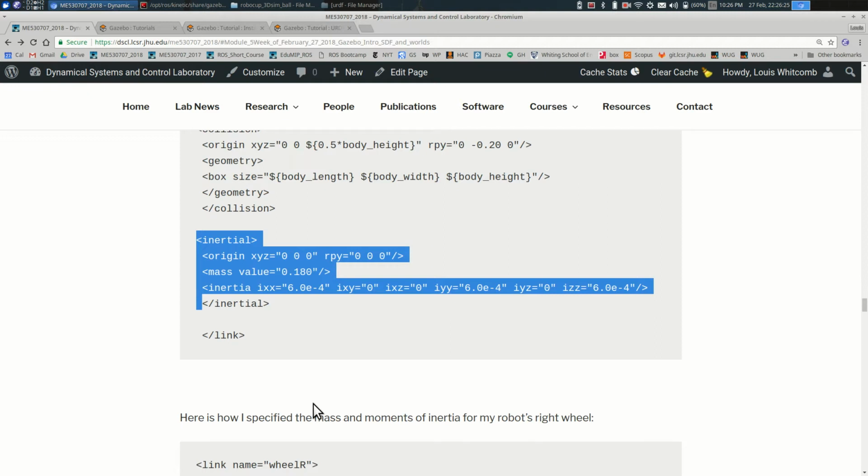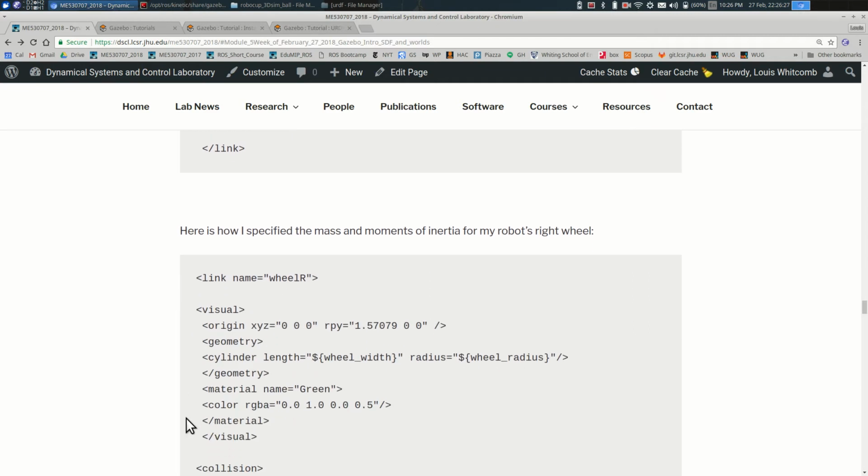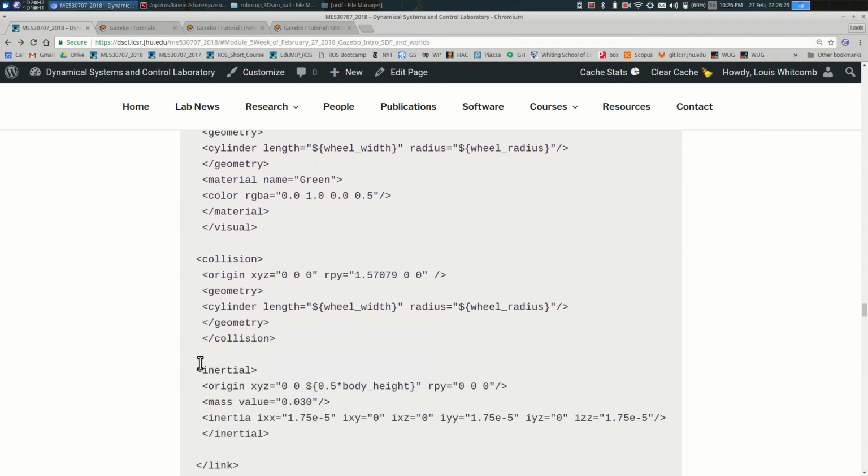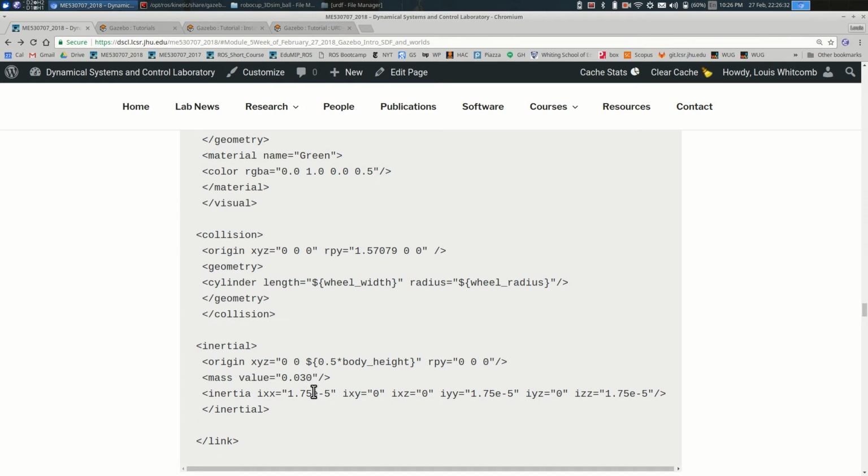So they're pretty small numbers, and the wheels themselves are even smaller. So the wheel looked like to me it was about 30 grams. And when you run the numbers for the moment of inertia for a cylinder that size, it was something on the order of 1 times 10 to the minus 5 kilogram meter squared. So really small moment of inertia for that plastic disc.